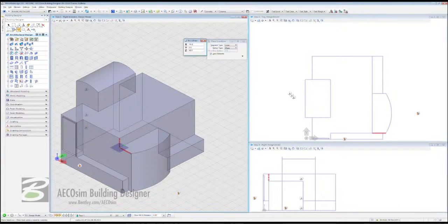Click once, hit the F key to rotate your AccuDraw compass, come all the way down to the intersection here and click. AccuDraw and AccuSnap are helping us out to do that so efficiently and coming out into the model. Once you've done that, you head north and you can see AccuDraw, AccuSnap is helping us out wherever we go, throwing out construction lines for us. We need to click there once and there to join this whole thing up,